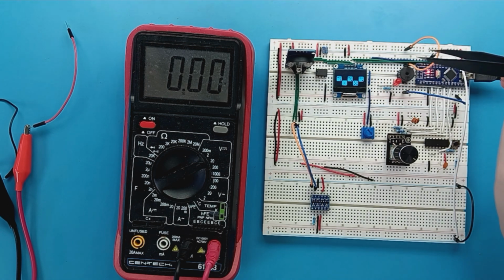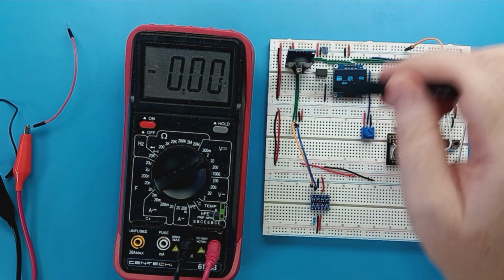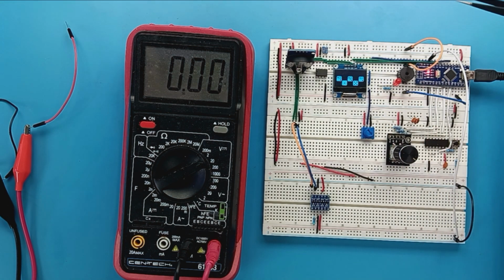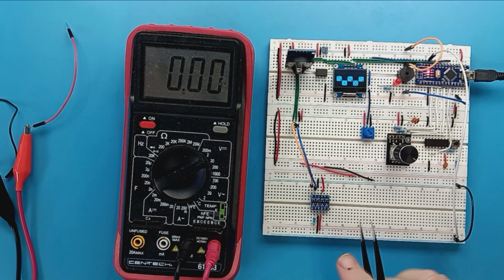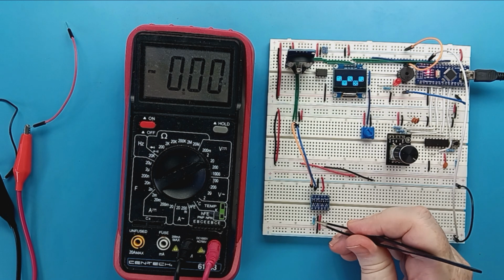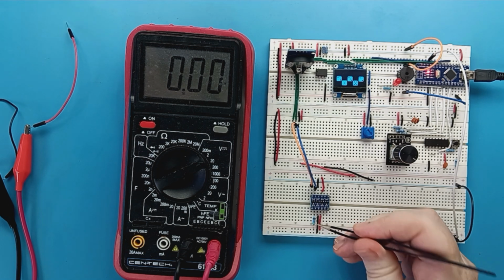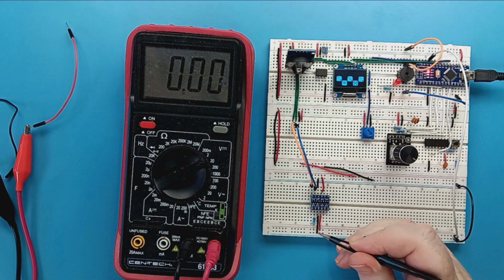So the I2C interface that I'm currently running on this side of the board on the top half is a 3.3 volt I2C interface. What we're going to do is use the logic level converter to convert from 3.3 up to 5 volts. So as I say, we've got the 5 volt rail in place. The only thing I'm doing on the 5 volt side is adding a pull-up resistor on the 5 volt side.